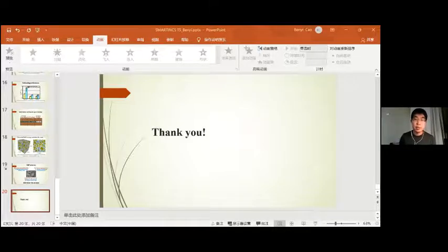The swelling capacity of SAP has not been lost because the absorption and desorption process is completely reversible. So even if it has released the water during the cement hydration process, after encountering the ingress water from the groundwater, the SAP can still swell again to its full capacity. Therefore, I would say the SAPs are fully saturated and the swelling capacity is not affected.